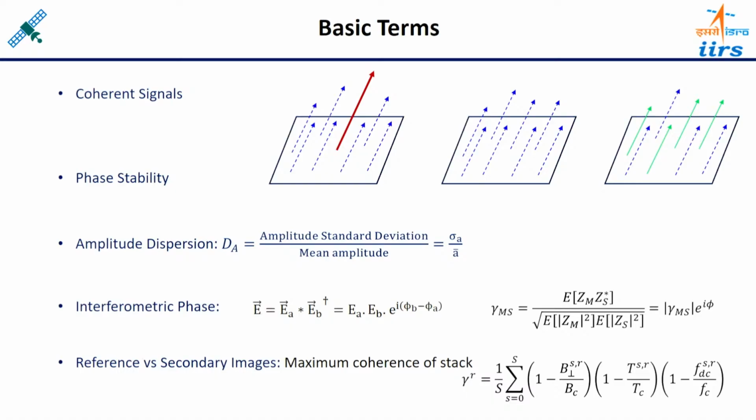And the third situation is, if you consider the third image as a reference, then again you make pairs between third and second, third and first. So third and second is 1 pair, third and first is another pair. If you calculate the coherence for both the pairs and add both of them, then there are now 3 situations. In the first, the first image is the reference, and you add the coherence of both pairs. Then the same for the second and the third.